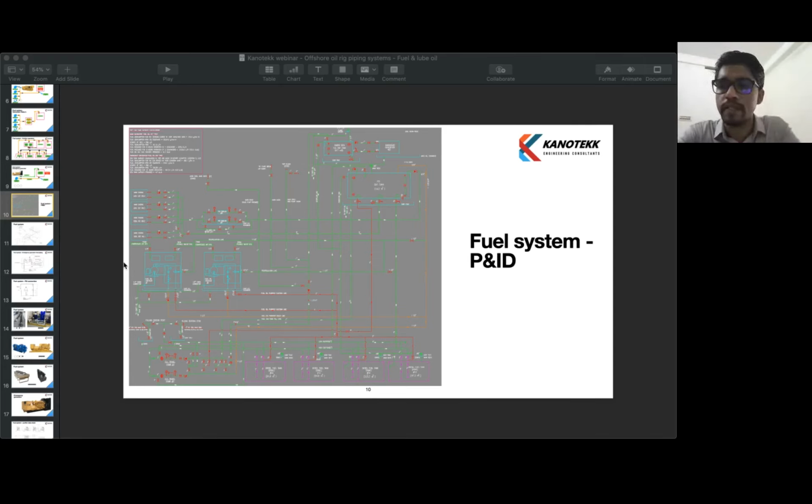The storage tanks, which we described earlier, are also called settling tanks, where the fuel settles, like water and fuel, and is stored there, and there will be a settling action. Like there will be segregation in ships, but in offshore oil rigs, the storage tanks are hull bottom tanks, so settling action is not very effective here. And this day tank provides the fuel for equipment.